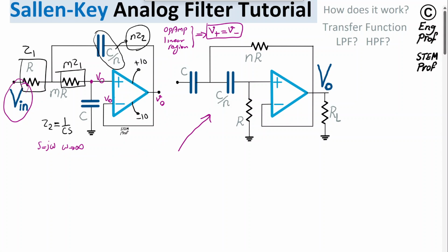On the other hand, intuitively for this topology, with the same argument, when the frequency is low close to DC, caps are open. When caps are open, nothing can go through the filter, so input Vin cannot go through.